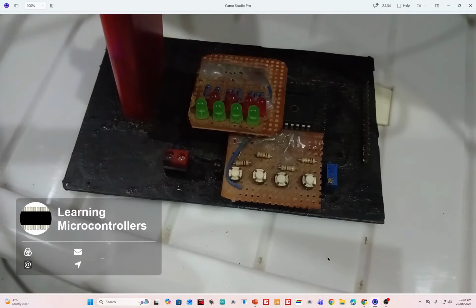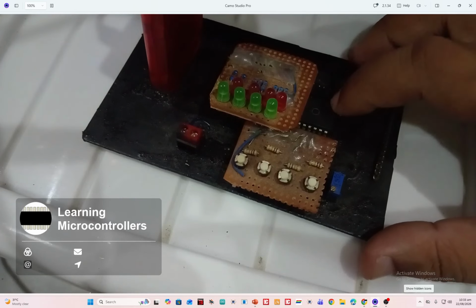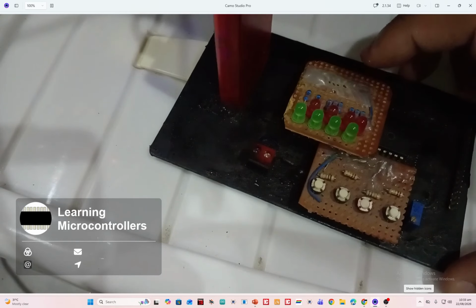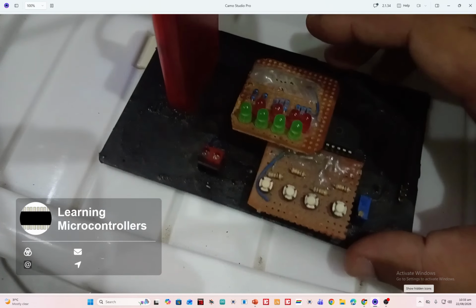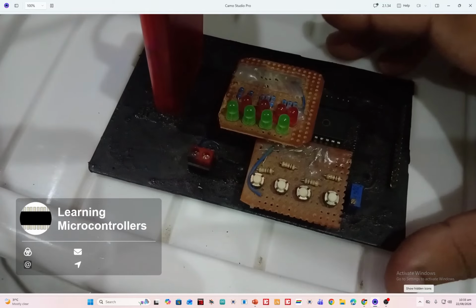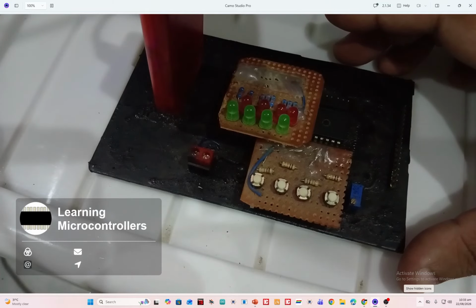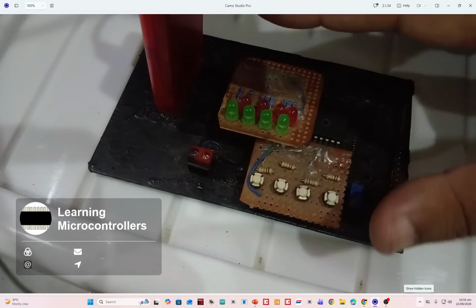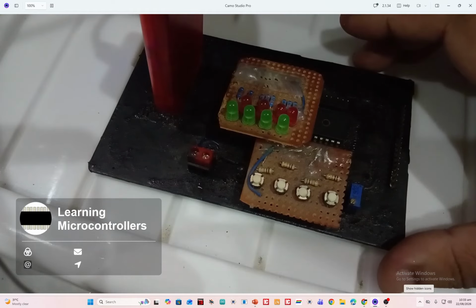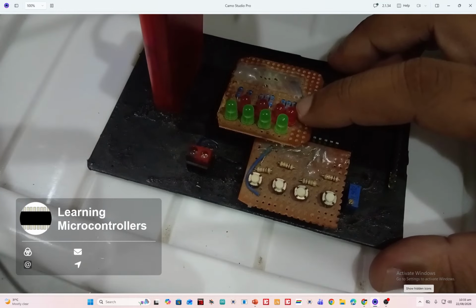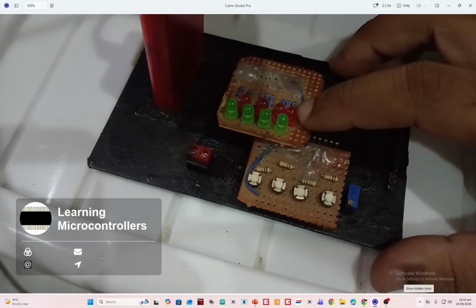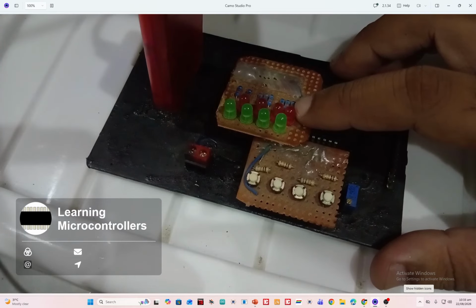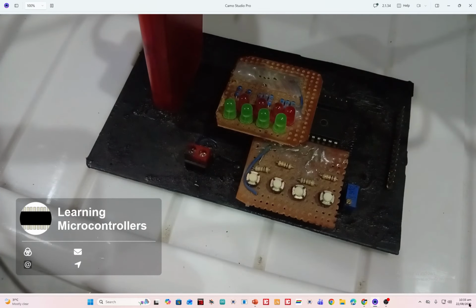So guys, this is the hardware that I have over here. You can see I have just connected a shield. This is my PIC16F877A. Here I have the PICkit 3 programmer tool, which will program the circuit and will also be responsible to power up this circuit as well. I will use 5 volts coming from the PICkit 3 to power up the circuit for demonstration. Here I will use this LED. This is connected to pin number B0. So this will be the LED that will blink once we write the code. So let's get to our MPLAB X IDE.